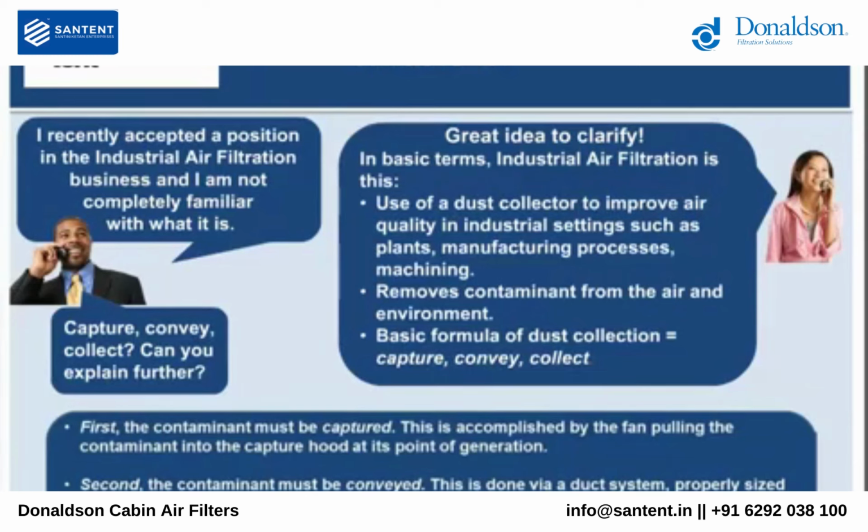Second, the contaminant must be conveyed. This is done via a duct system, properly sized to maintain a consistent minimum air velocity required to keep the dust in suspension for transport to the collection device. Finally, the contaminant is collected. This is done via a variety of devices, depending on the application and the contaminant being handled.